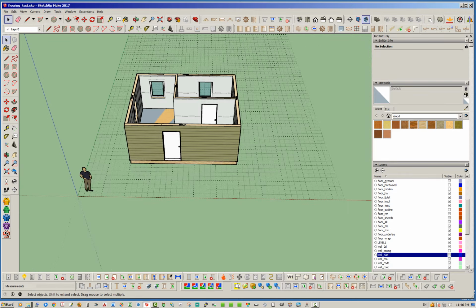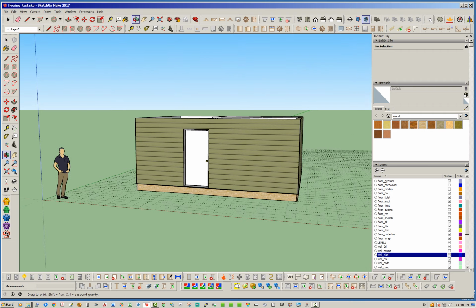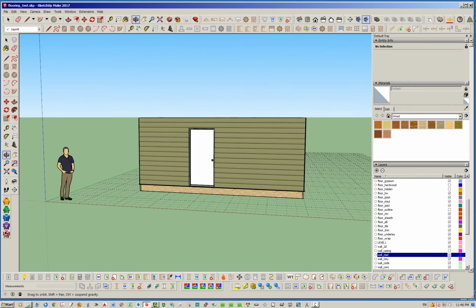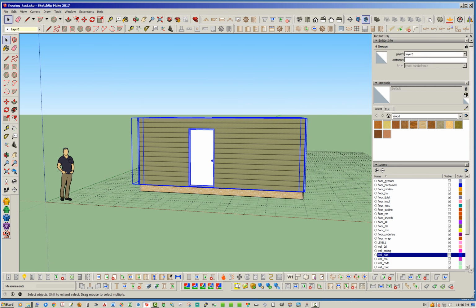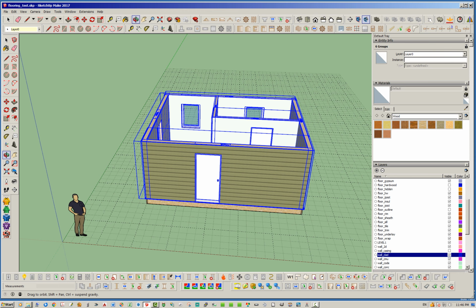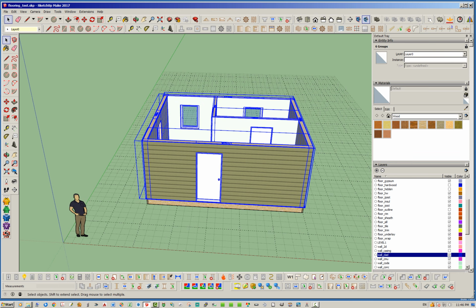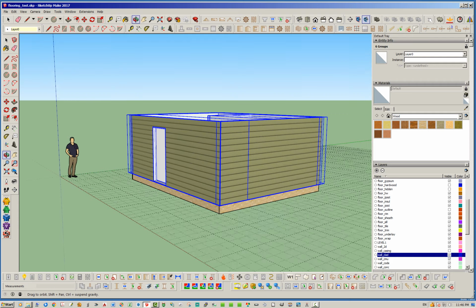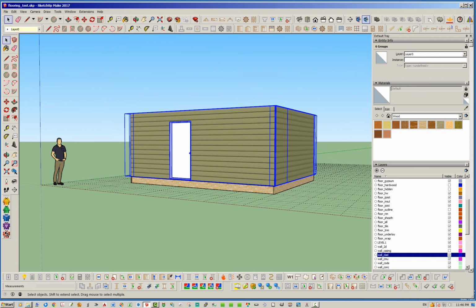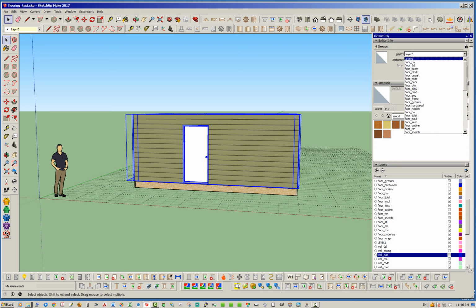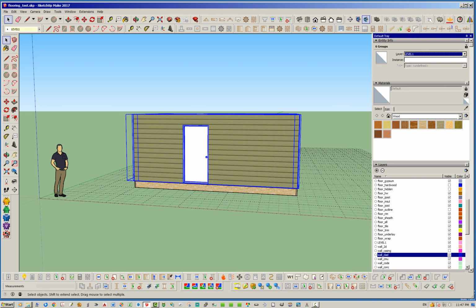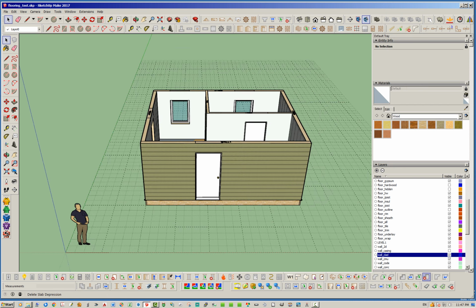Now, what I like to do is turn off my walls just to get the clutter out of the way. So I'm going to take these walls and select them, and I've got 6 groups, 6 walls, right? I've created another layer here called level 1. I think I showed this in another video, but I've actually started doing this. Normally the assemblies are created on just layer 0 or the default layer, but you can put the assemblies themselves on another layer, and this makes it handy because if you want to toggle off all of these, you can just turn off that layer or tag, right?